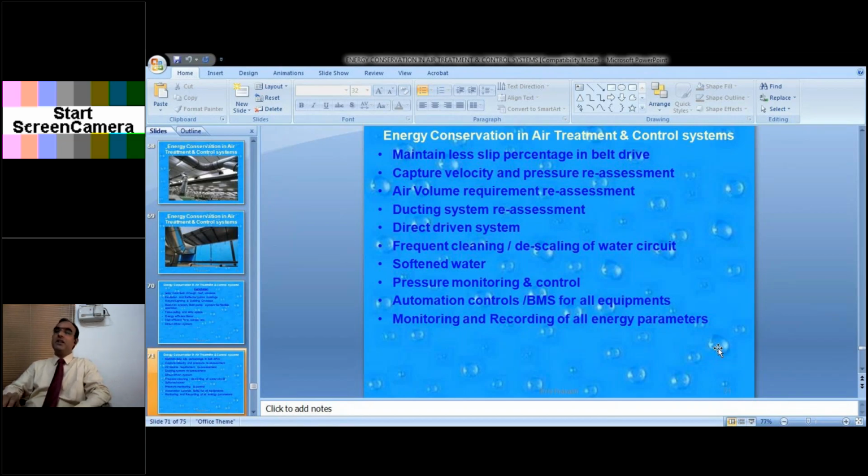This only happens. Without knowing, we just go and do an audit. For this CMH, they will tell us the motor is taking this and the fan is delivering that. Where we can reduce direct drive, belt drive, that is what we will see, and pressure. But once we know the exact requirement of the process, then we can tell them confidently that there is a scope, with measurement.